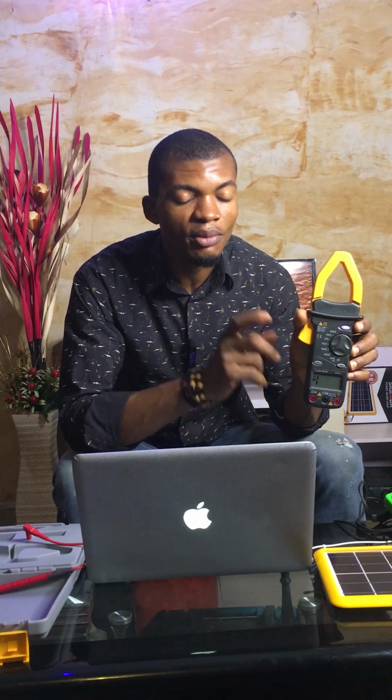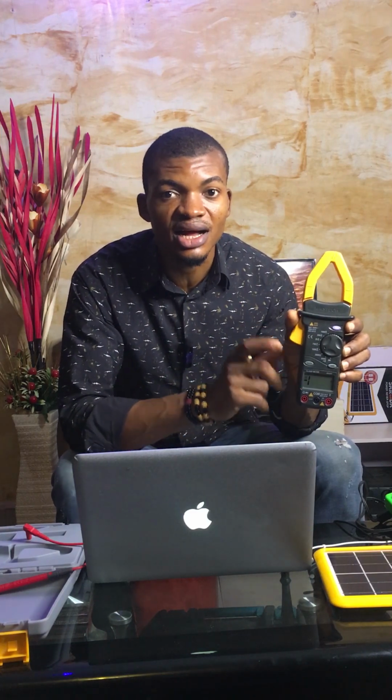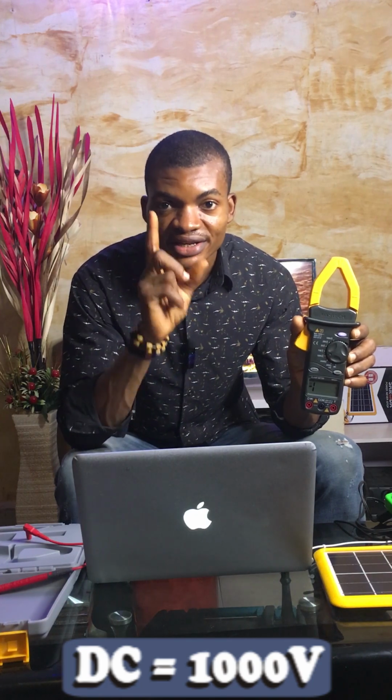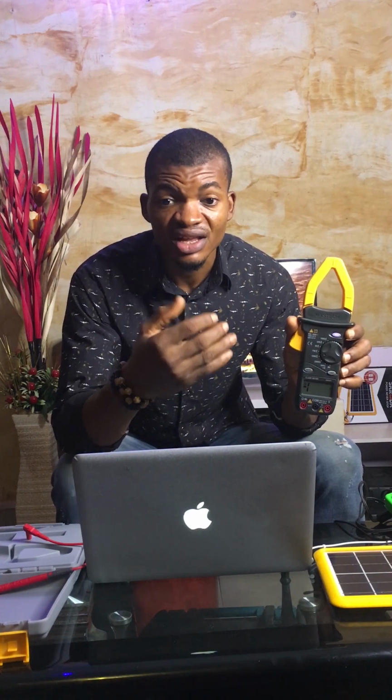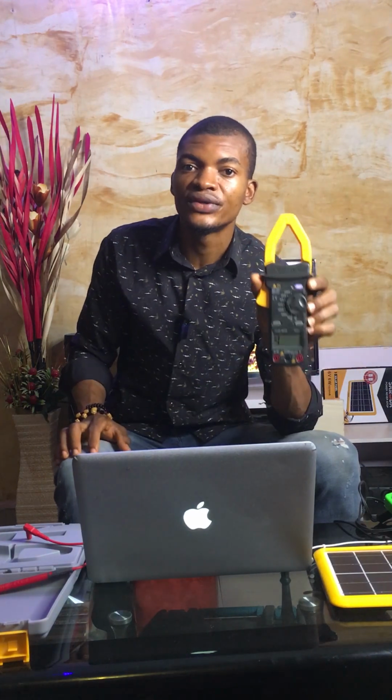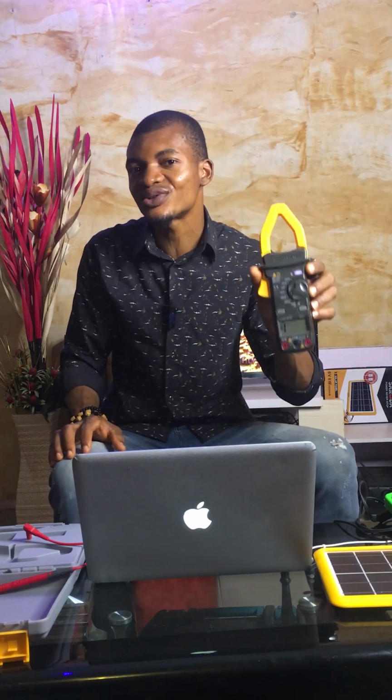And don't forget that when measuring this, you are measuring according to the specific voltage that is required. The maximum at which this multimeter can handle is 1000 volts in DC. Because it is DC, you can measure from 0 to 1000. Above that, it will not be compatible with the meter, which might cause damage to this particular meter.